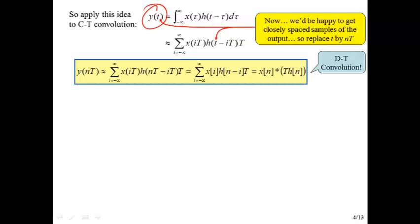Now we'd want the output, we would only need to know it at a certain set of closely spaced samples, because the output's going to be the output of a discrete time system. And as long as those samples are closely spaced, we know that we can run them through a DAC and get a continuous time signal out of them. So what we're going to do is replace this t by the values spaced by our sampling interval, just like we did here and here.